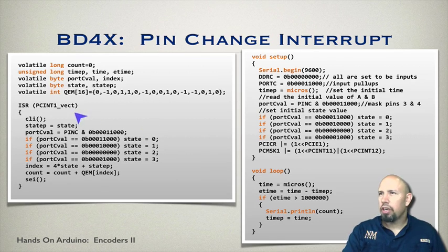So here's my interrupt service routine. I clear the variable. I set the present state to become the past state. Then I read in. The states here, we saw when we looked at the different transitions previously, states 0, 1, 2, and 3. We're going to use those same states like we did when we worked with the array.